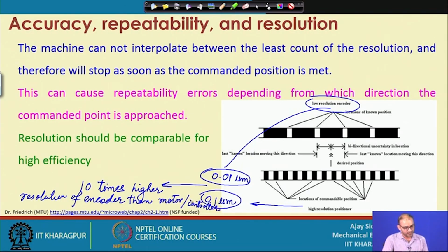Right. So, this way you can get the complete capability of this machine, because without that, whatever sophisticated motion controller you are using, if you end up with a low resolution encoder, ultimately you are operating with low resolution. Low resolution means you end up with a very large amount of motion steps, but when we say high resolution, that means the step size is very small.